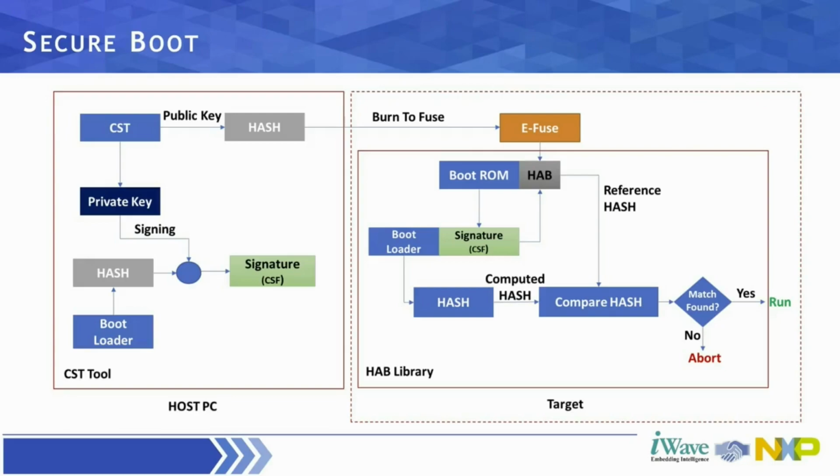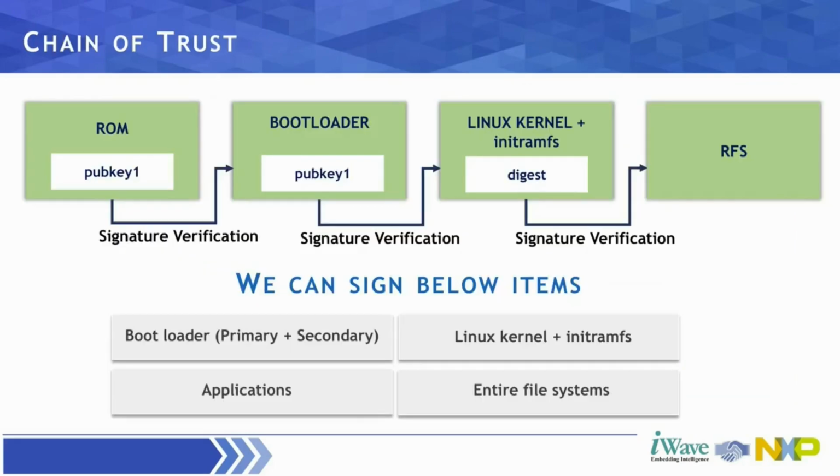Now, as I mentioned before, in terms of building the chain of trust, information has to be passed on from layer to layer and has to be exchanged confidentially between the different components. The chain of trust is the only way to ensure that no hacker has interfered in this communication chain. So this is the task of the root of trust, and why it comes in and becomes the building block for major secure storage and cryptographic operations.